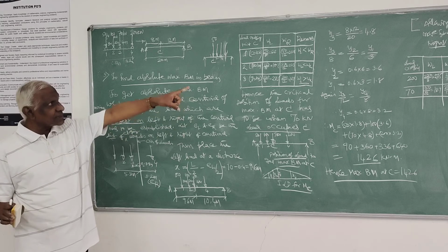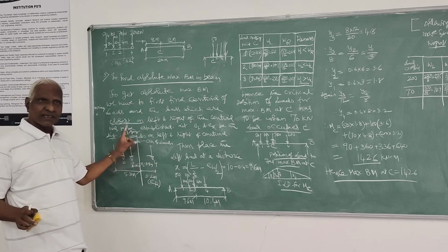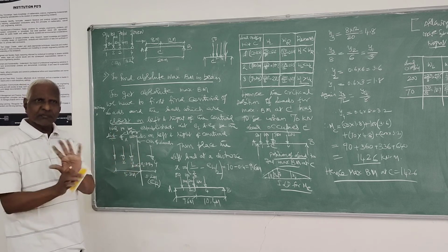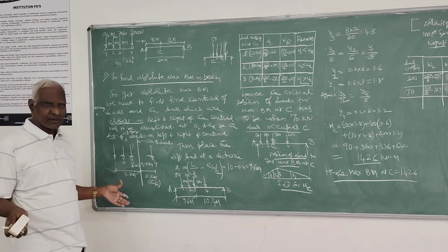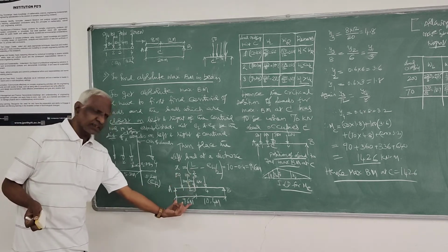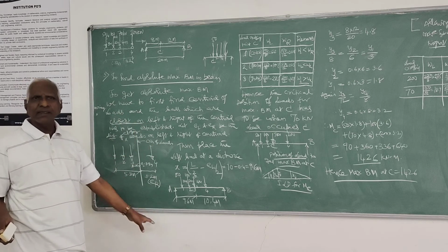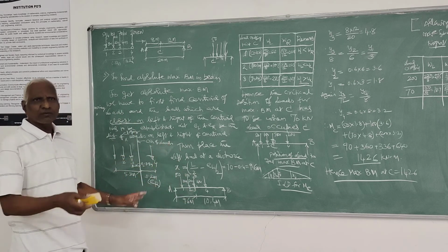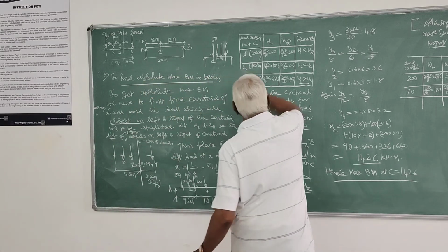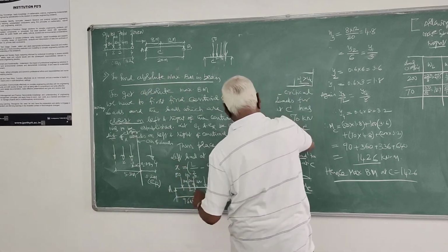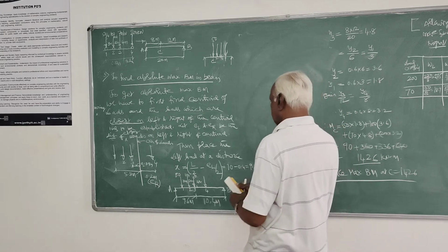Then in finding the maximum and minimum, you are preparing the table. Here the criterion is this. If you have understood, absolutely things are very, very simple. So this location, if you know, then for this position, you use the influence line diagram and work out the bending moment. So for this position, next we continue. So this is the position of load.